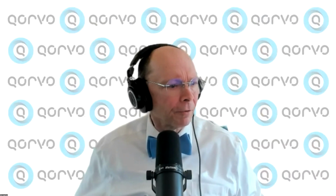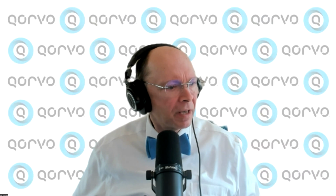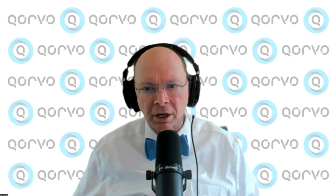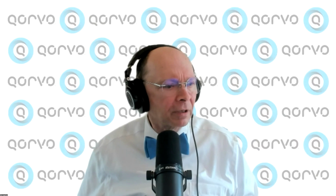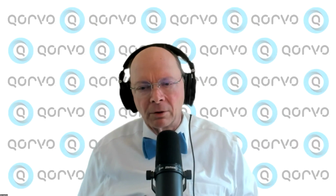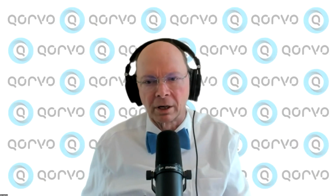Yeah. And there's a fair amount of information which it can dead reckon pretty well for you. Specifically, it adds some sub-threshold conduction. I've made enough MOSFET models that I know they have sub-threshold conduction, and I know the parameter doesn't vary by a factor of 2, so I just throw in some sub-threshold conduction.